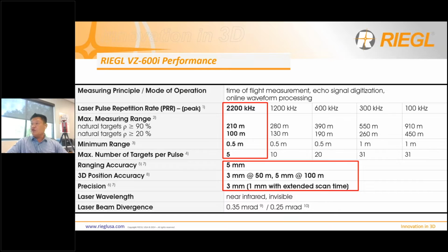It's simply because we use time-of-flight technology, so we just have to slow down the mirror for that pulse at longer range for the timer and encoder to receive and log it properly. We have an incoming pulse, and we can calculate the distance by the timing received from the incoming pulse.